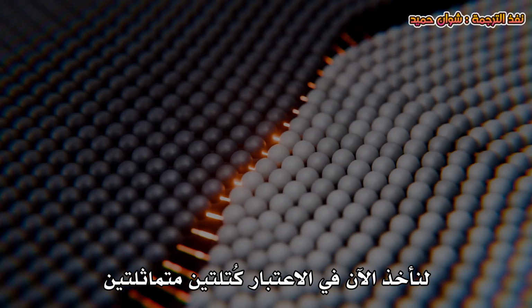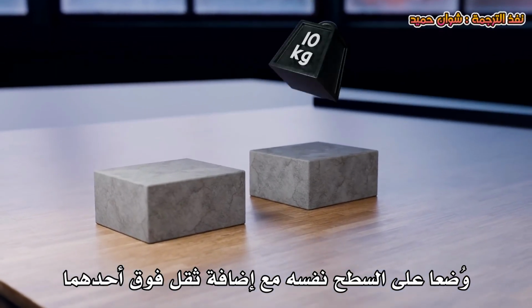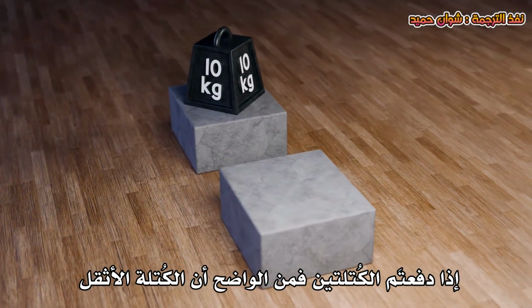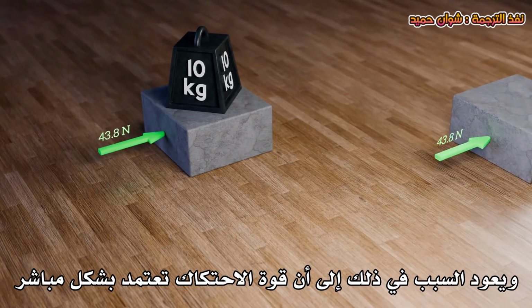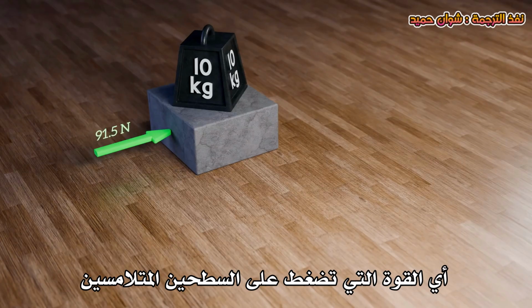Now consider two identical blocks, both placed on the same surface, but add a weight on top of one of them. If you push on both blocks, it's clear the heavier block requires much more force to overcome static friction. This is because the friction force depends directly on the normal force, the force that presses the two contacting surfaces against each other.